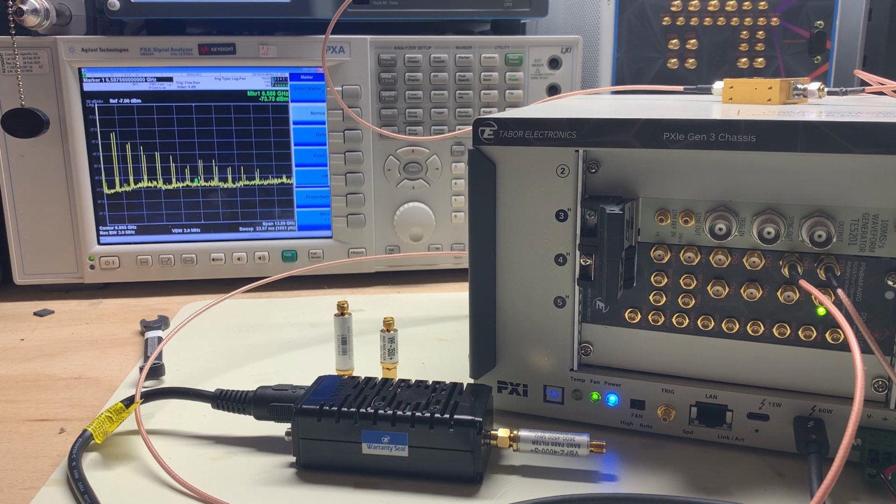So we can use each image, if we choose to, as a way of upconverting our signal. So we could just pick the 4 gigahertz image that we've got there and tune the spectrum analyzer to plus 75 megs off that carrier, and there you can see we've got a pulse. However, there's a lot of spectral activity inside that 13 gigahertz of span, and so if I go back to full span, we can see them all.